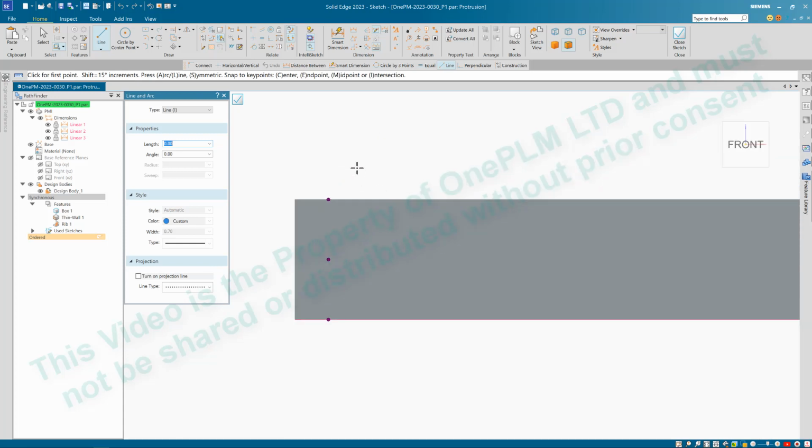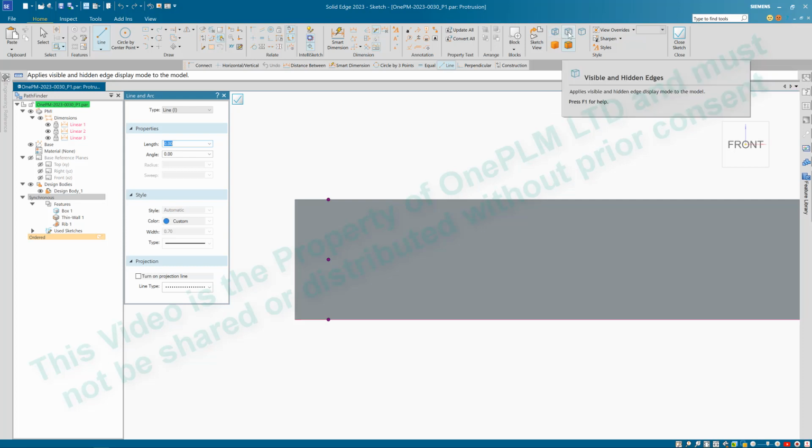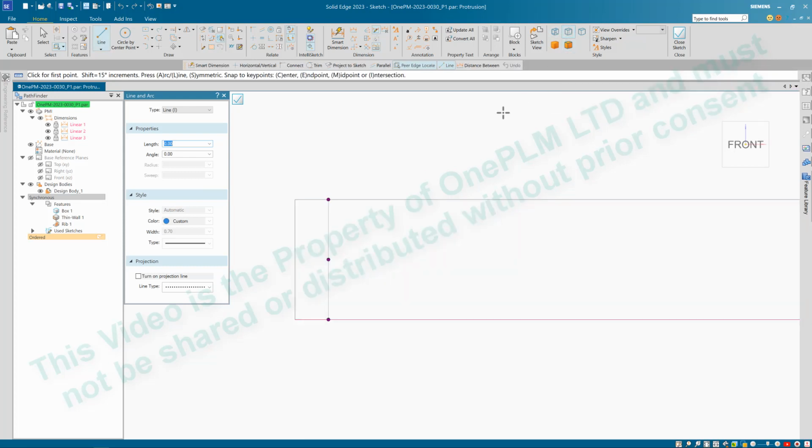So we're zoomed in on the left hand side. What I want to do now is see the underlying geometry. So up here towards the right hand side of the bar, we've got this option to show the wireframe or wireframe with hidden edges. If I click on there, that's going to allow me to see this as a wireframe view. Notice our line command has automatically started, so I'm going to choose the end point of this line that we can now see.